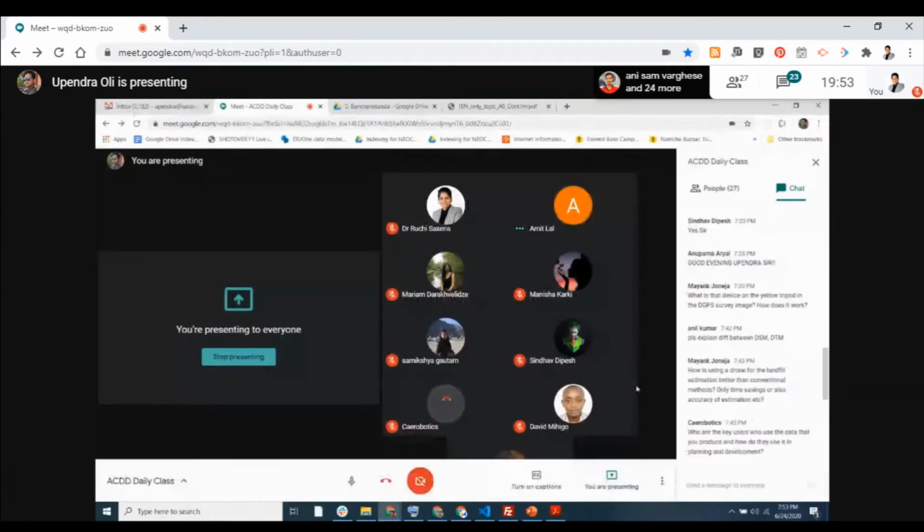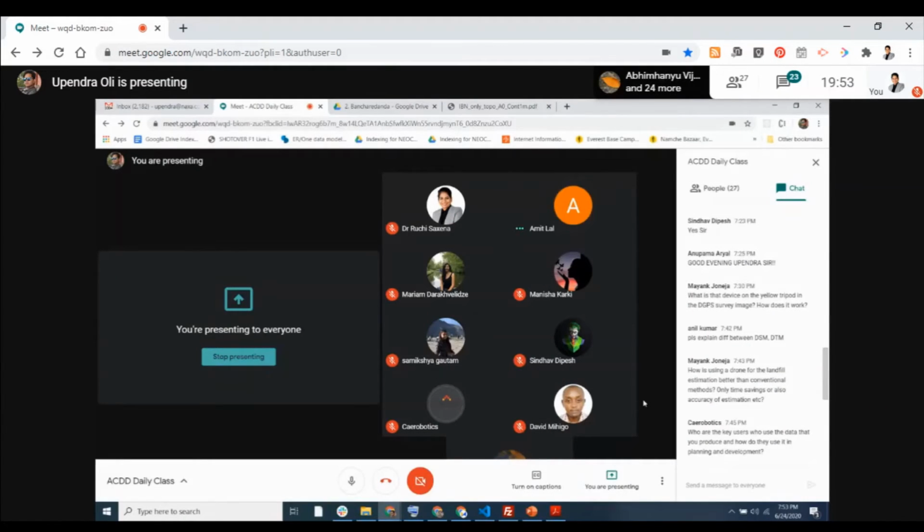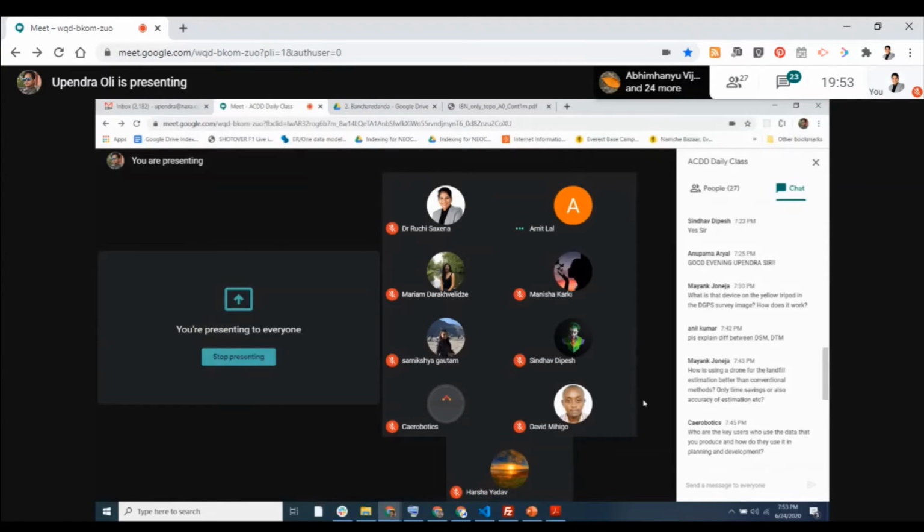Okay. So Mike is asking, how do you correlate the geotags on the photos taken from the DJI with the multiple GCPs? The DJI GPS was just for preliminary georeferencing, because the DJI GPS is not accurate enough, and its accuracy lies around 5 to 10 meter. So just to match the images and orient the images, those coordinates are used from the DJI drone.